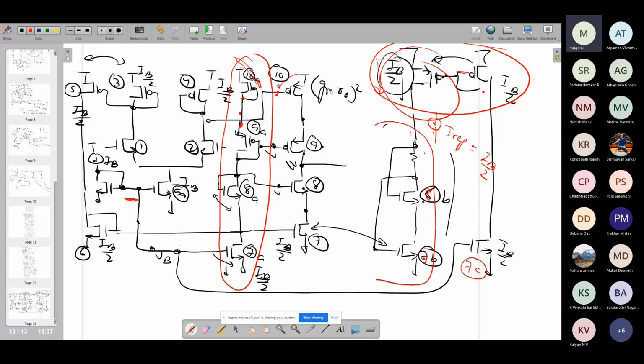These are like our cascode current mirror with reduced swing. Here we can use this particular bias point for M8 directly. So this can be used for biasing M8. Likewise, we can also use another branch for biasing, say, M9.